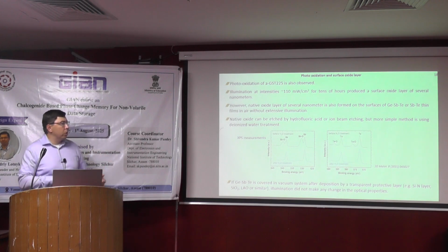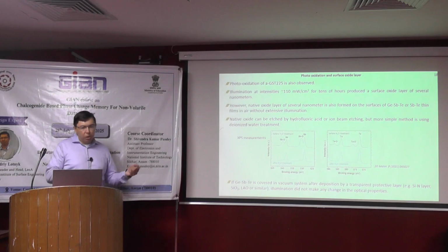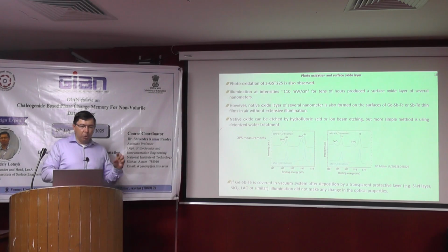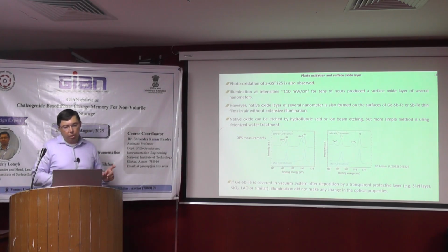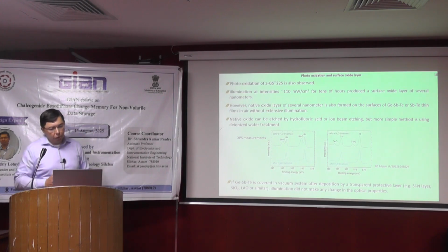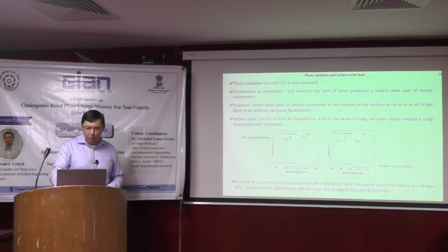If you want to use optical measurements, you deposit a material like silicon nitride, silicon oxide, or lanthanum oxide, or similar optically transparent materials, which do not influence the properties of your system much. Or, if you have the possibility, you can deposit contacts for electrical measurements directly in the chamber.